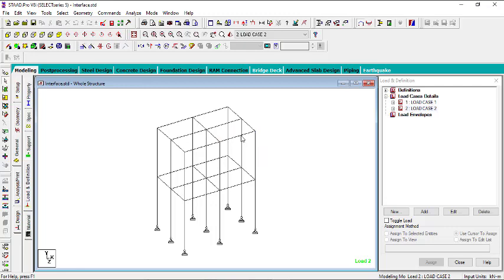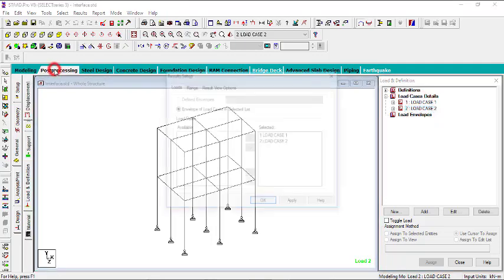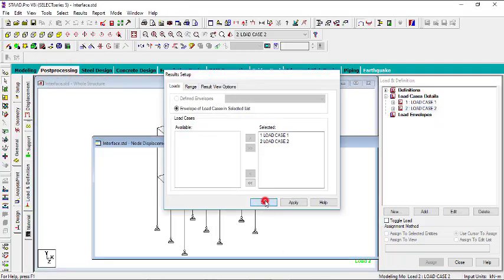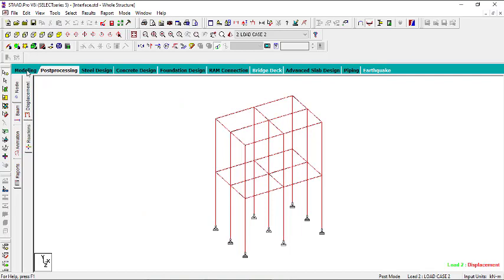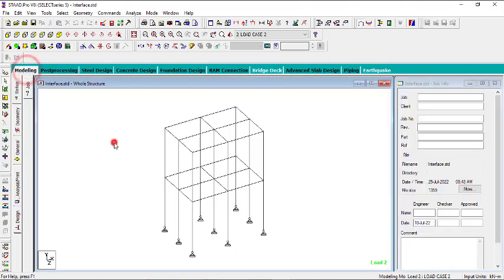In this episode, I'll be showing you how you can design an isolated pad footing in Staad Pro. The first step in doing that is you should have your model ready and you should have analyzed it. So you have your load cases and everything. The analysis should be there. If I go to post processing right now, you see that I already have that, which means I've done the analysis. If that is okay, then you now go to Staad Foundation.